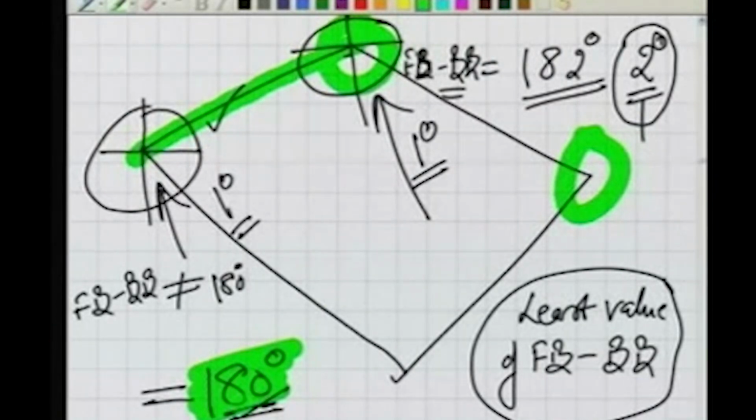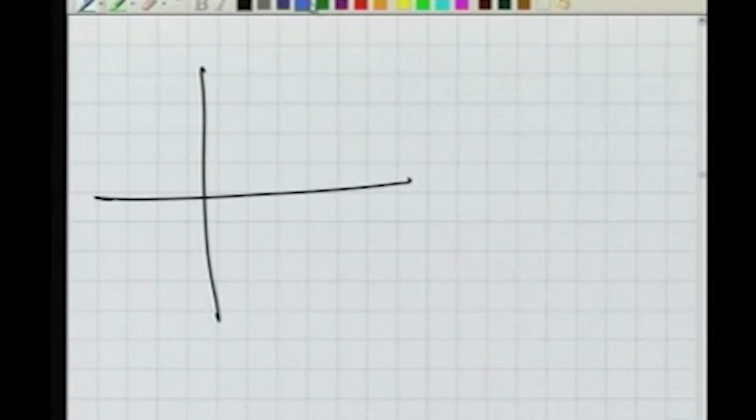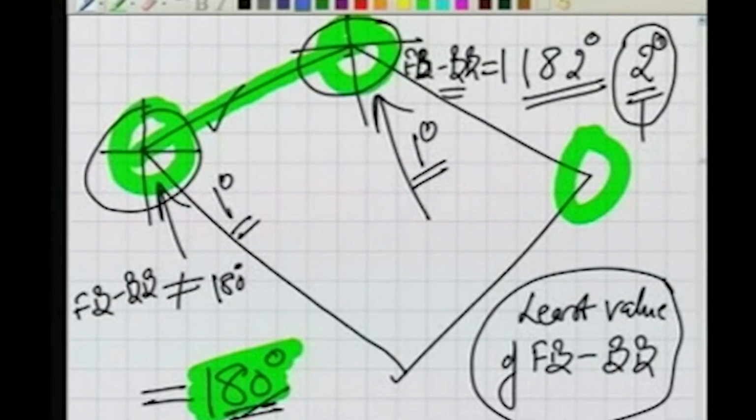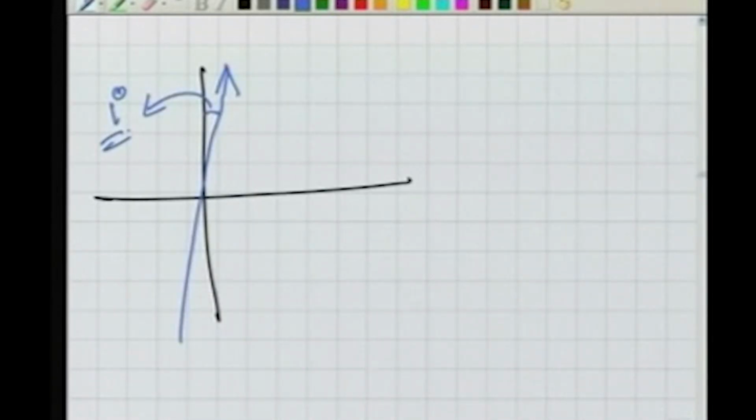Well, once it is done, we assume that whatever is the fore bearing here is correct, and whatever is the back bearing here is correct, and whatever amount of correction, for example, because of the local attraction, the north was turned in this direction, and this is 1 degree of error. And we know, as we have seen in the previous case, we had applied some corrections here, and we know it is 1 degree.